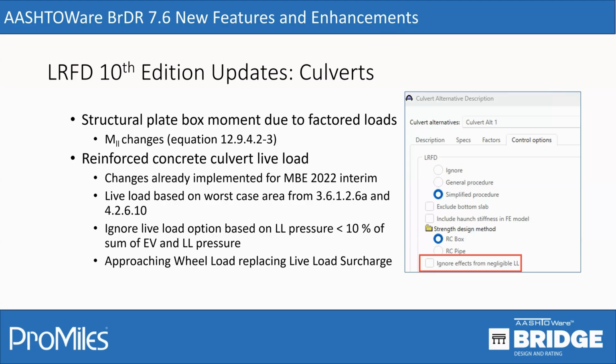for scenarios which may have ignored the live load in the previous spec may not ignore the live load for the new spec unless you check this box here, and this criteria is satisfied for the live load pressure less than 10% of the sum of the vertical load pressure and the live load pressure. Also, similar to LRFR spec, MBE spec, the approaching wheel load was introduced, which replaced the live load surcharge for culverts. Okay, with that, I will hand over to Carolyn Coyce.